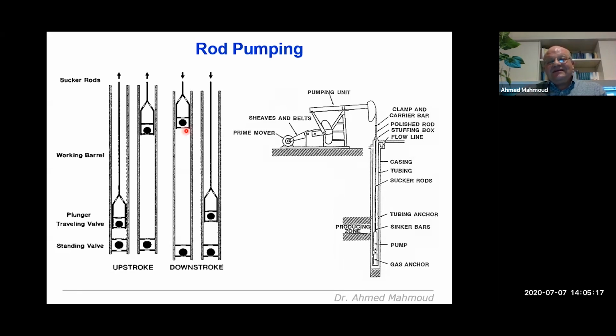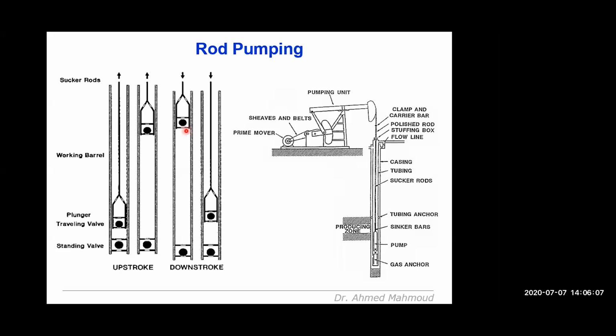In this separation, it will add a bit more load and cause some sort of rattling in the mechanical movement of the sucker rod. So you will have to apply more power, and this rattling effect is not good mechanically for the sucker rod. Yes, it will reduce the volume coming to surface if separation has occurred.